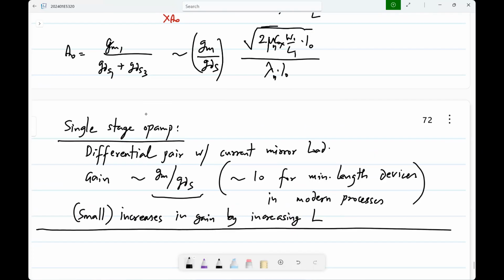So we want to have an integrator, but with a higher DC gain. So how do we do that? Yeah, but how much will you reduce it? It will also affect other things, right? Because you want to change only A naught, because if you change I naught, the GM also will change, and then the unity gain frequency will change, right?